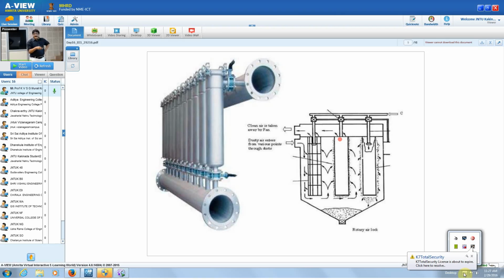This is called dust resistivity. So it cannot treat any gas further. So at that stage, the whole system is shaken thoroughly, and pure air from compressed air, this C means compressed air, is sent in the reverse direction, just like backwashing in the case of a rapid sand filter. So this bag is completely cleaned. All the dust falls here. This is called the dust collector.